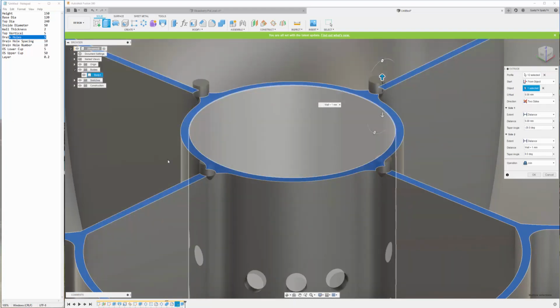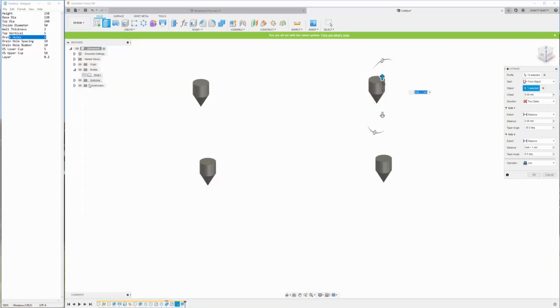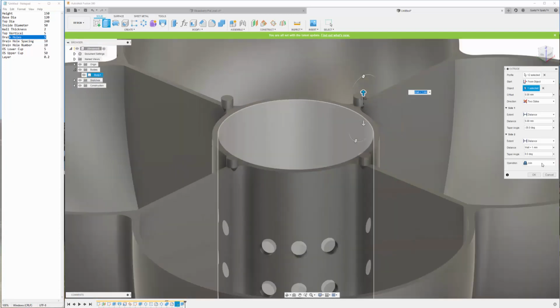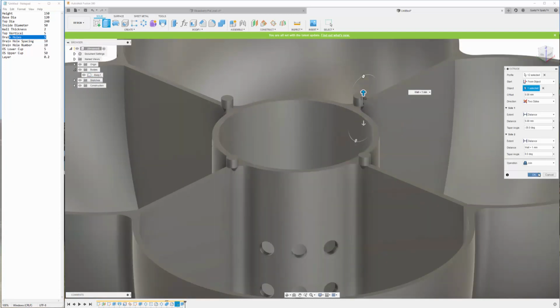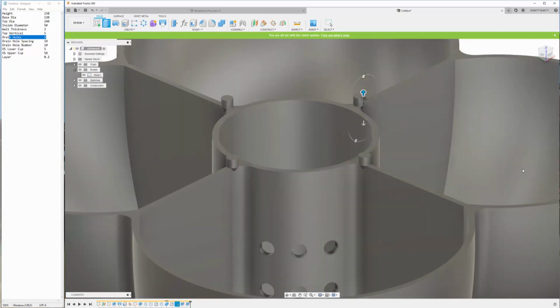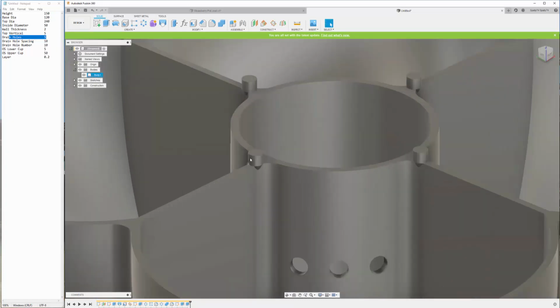So what I've done now, so as to turn this body off, is I've created tips on it. So now if my wall's only 2 mils thick, it'll taper down to hit the wall, or if it's too thick, it'll actually just basically be absorbed into the join. So now I hit join and I go OK. So now I have my pins.